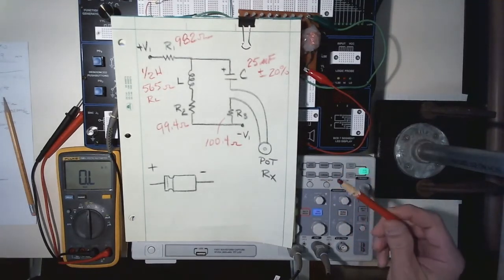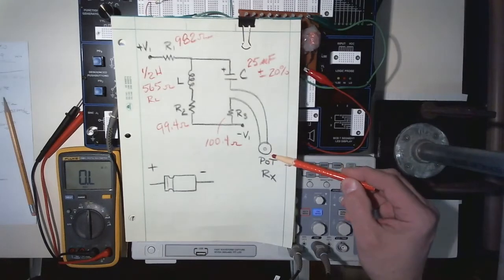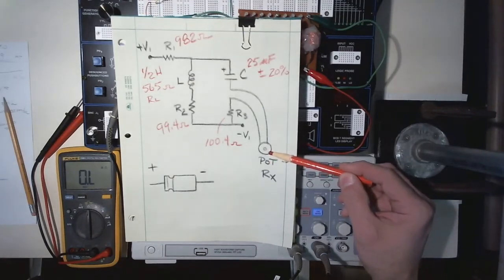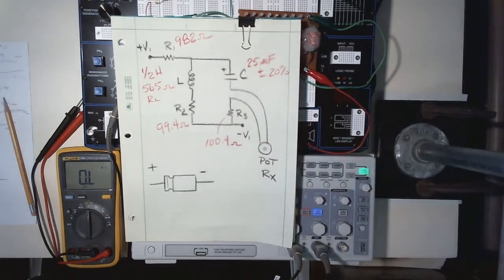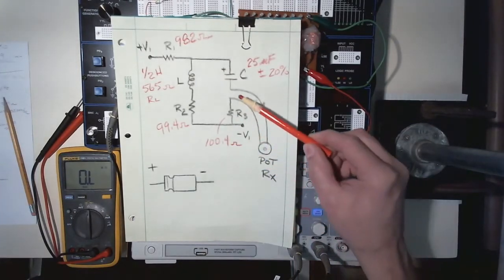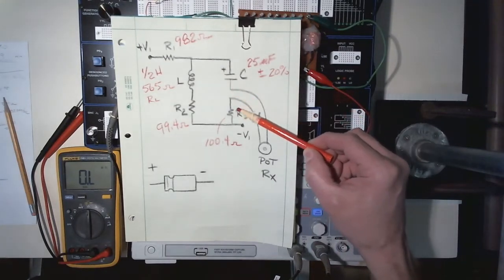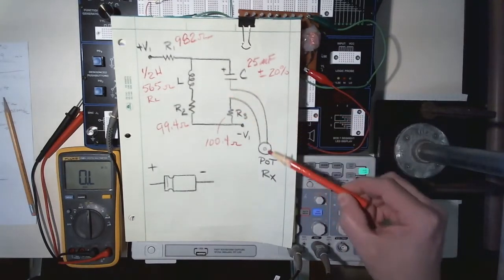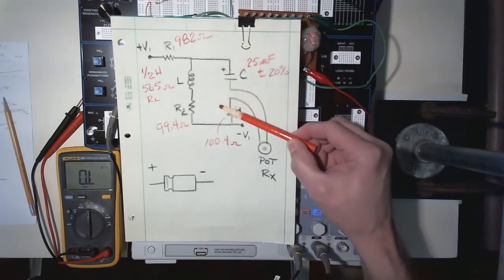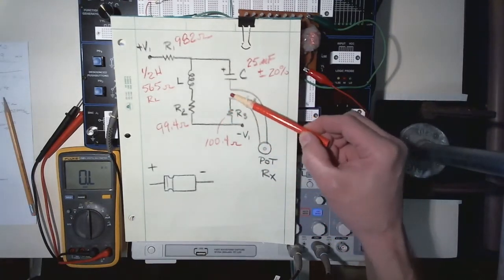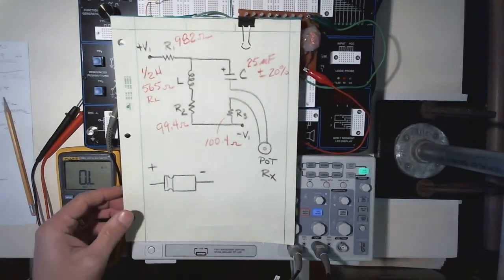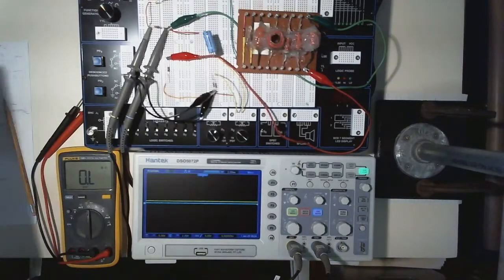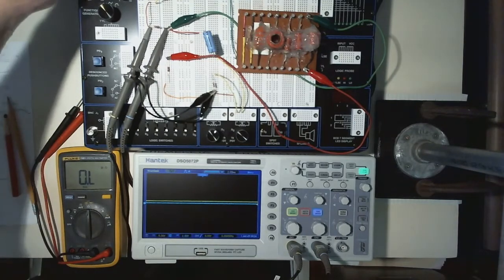to our experimental value? This is our potentiometer, like I say. We'll measure that a little bit later. And finally, this R3, you've got 100.4 ohms right there. And in your calculations, I actually separated and had this RX right here and R3, but some people choose to combine this all into RX, just to make your calculations a little easier. So with those values, let's go ahead and fire this thing up and see if we can take our data and get on with this.